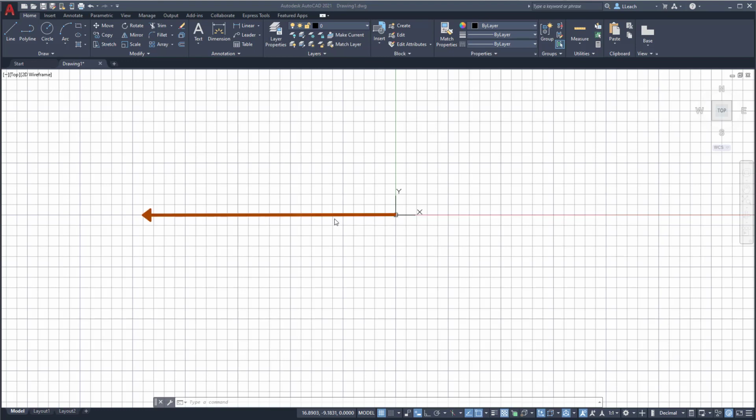Anything to the left of that origin is going to be obviously a negative X value. Anything above the origin is a positive Y value, and anything below that origin is going to be a negative Y value. Absolute coordinates are measured from the origin. So depending on what distance or length each one of the locations that you need is, it's going to be measured back from this origin, the home base, the center of the universe position.